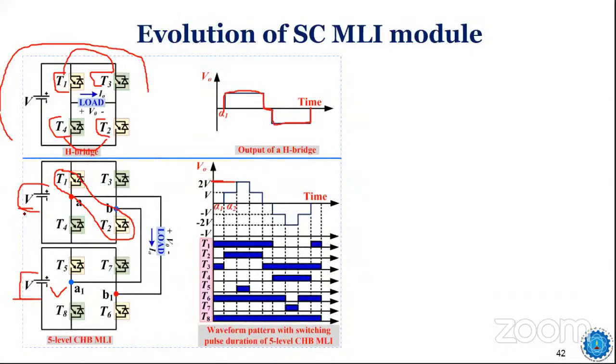So if you take the voltage, let's suppose here 50 volt, here 50 volt, I am getting 100 volt output. But why am I telling you this is not interesting? Because if you observe, you have got a multi-level staircase output. Harmonics may be reduced compared to this 3-level; 5-level has lesser harmonics, definitely. But the problem is what?